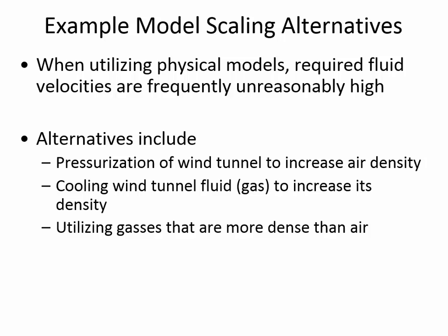And cavitation, remember, is a very localized low pressure that causes bubbling, and the collapse of those bubbles can cause damage, but it's also very noisy. So there's a lot of research that's done on trying to make submarines more quiet so they can be more stealthy. Model scaling can be used in a situation like that, where if you don't want to use a billion-dollar submarine for this research, you can't take it out of commission, but you can use small-scale models and change from one fluid to another. So you could use a more viscous fluid like oil in place of water, and it may give you advantages in terms of the speeds that have to be used for the scaling.